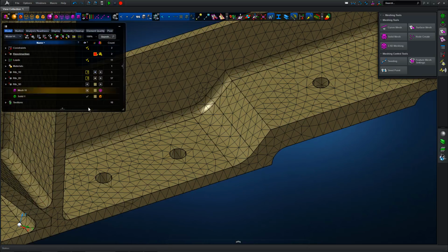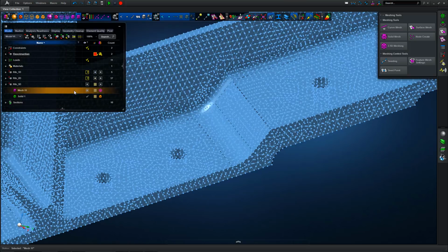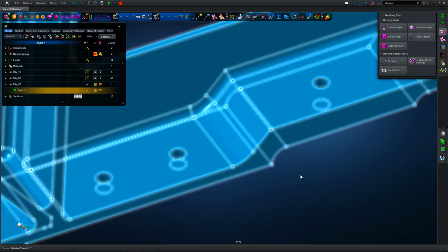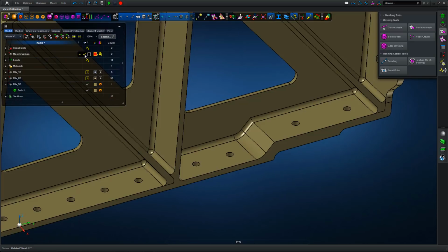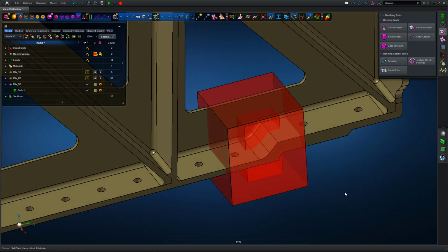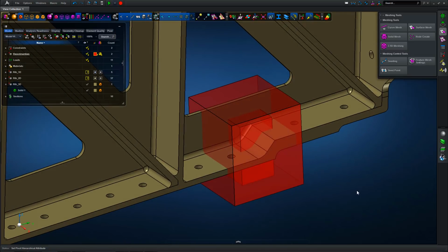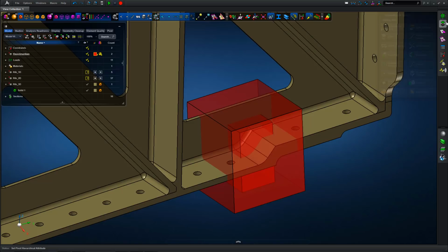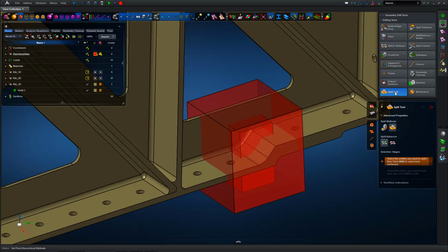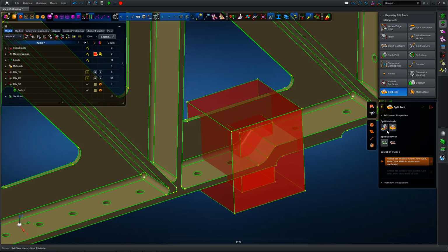So we could get into a scenario now where we might wish to locally manipulate the mesh definition so we've got more elements and more detail in a given region of interest. So we're going to look at some ways of splitting the underlying geometry. We've got some construction geometry developed, and this is going to be used to break the underlying rib 3D geometry into some discrete parts.